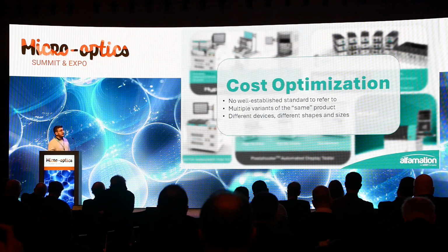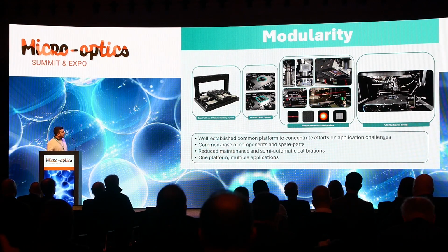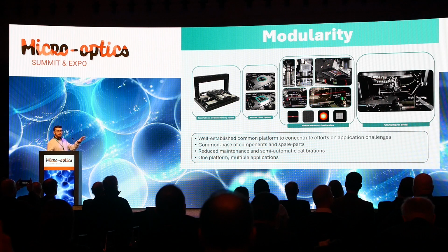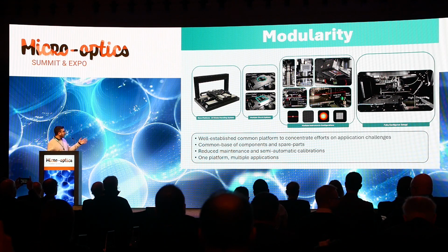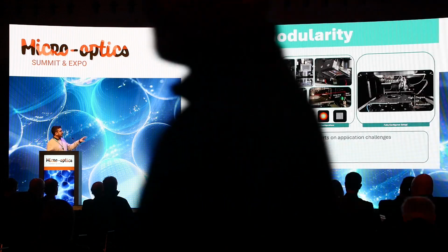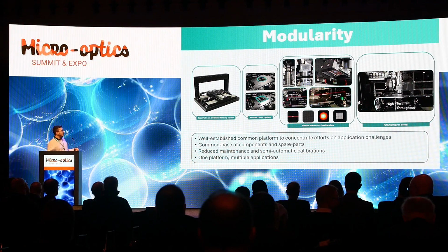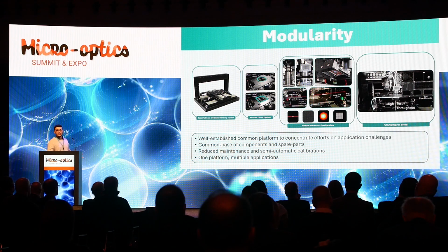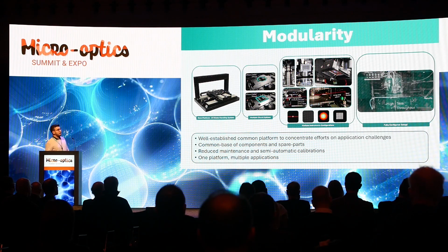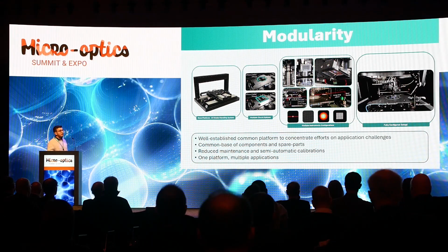And so a key feature of test equipment to achieve this cost optimization is modularity. That's why we try to design our systems combining different modules, starting from a base platform, in this case for wafer handling, a rail-based system, which is then combined with multiple track options where the wafer is loaded with different shapes and sizes, but also additional functionalities like wafer warpage compensation or vacuum retention.